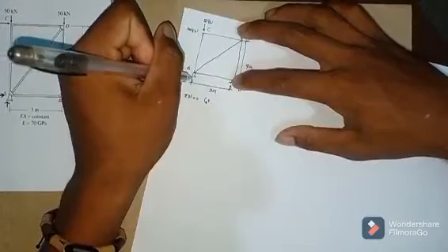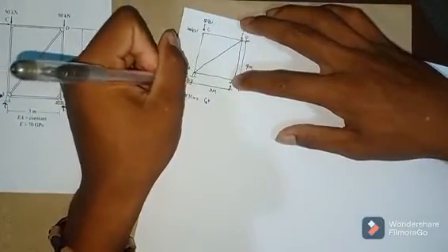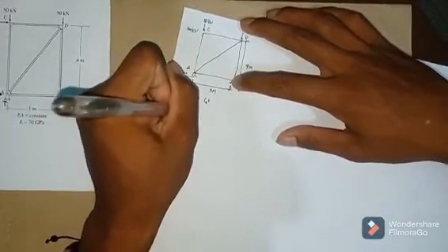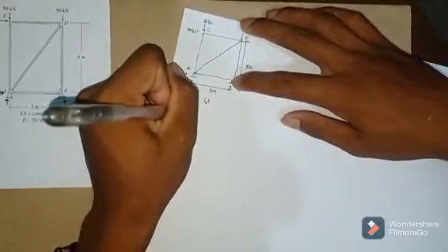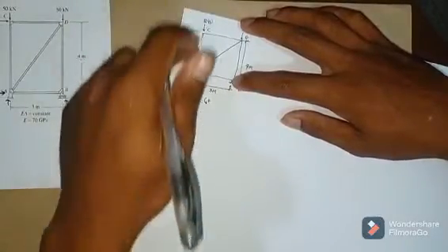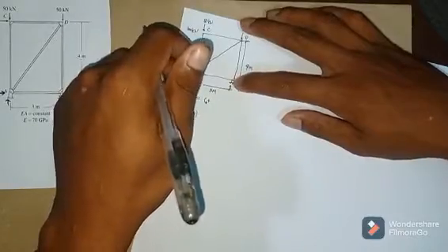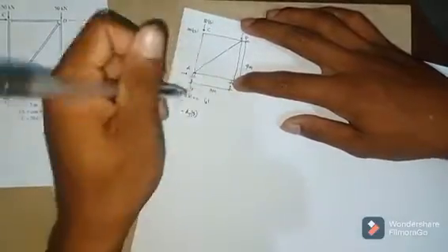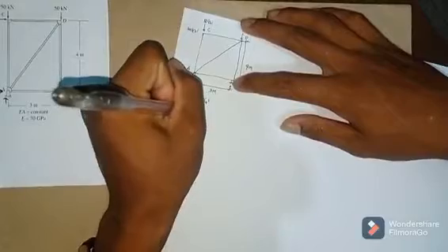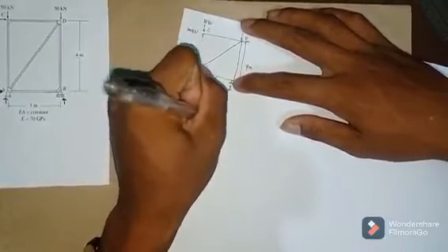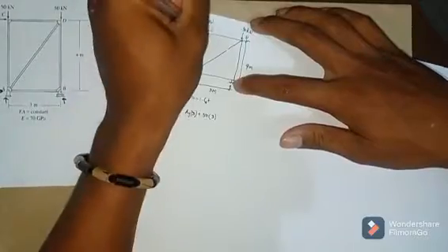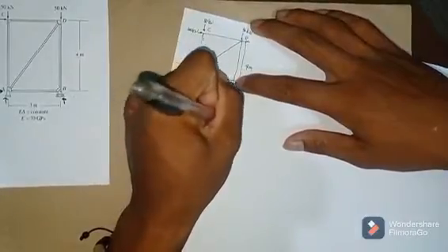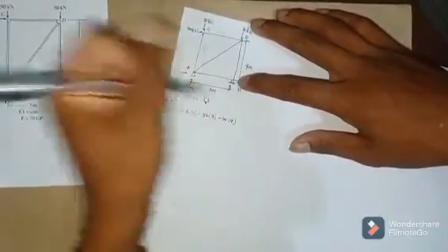So the first forces na i-moment natin is yung A vertical, which is AY times its arm length, which is 3, and then yung 50 natin, rotating clockwise, so it is negative, and then 50 it is rotating counterclockwise, so positive 50 times the 3, and then the 100 kN, which is rotating clockwise, so negative 100 times the vertical length, which is 4.